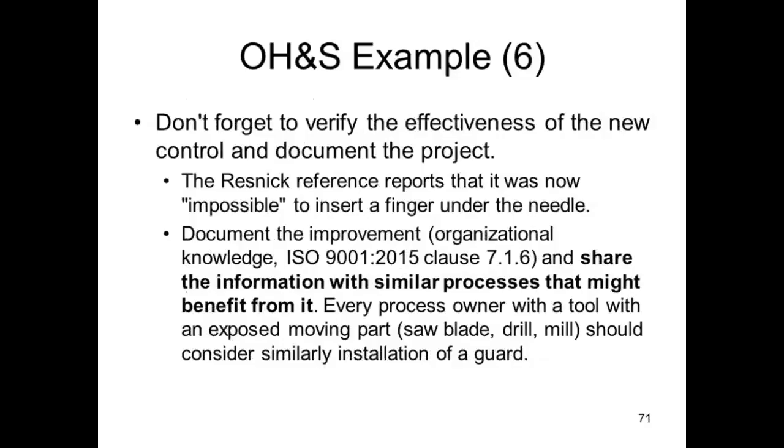Don't forget to verify the effectiveness of the new control. The Resnick reference says it was now impossible to put your finger under the needle. Document the improvement and share the information with similar processes that might benefit from it. So every process owner with a tool with any kind of exposed moving part should look at this similarly. Now, we take machine guarding for granted today. That was not the case 100 years ago.